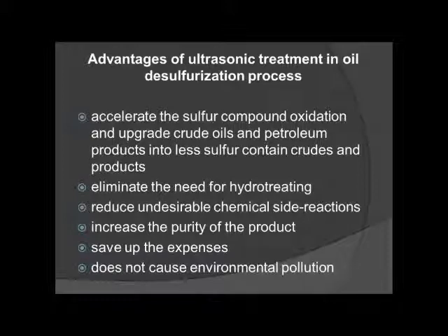And the advantages of ultrasonic treatment in the oil desulfurization process: it can be used to accelerate sulfur compound oxidation and upgrade crude oil and petroleum products with less sulfur content. And ultrasonic can be used to eliminate the need for hydrotreating, and this could reduce undesired chemical side reactions, increase the purity of the product, save expenses, and most important, it does not cause environmental pollution.